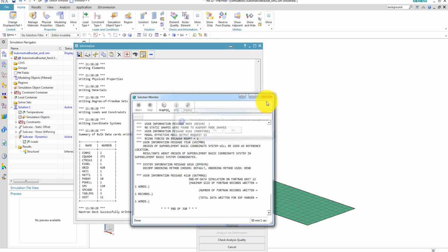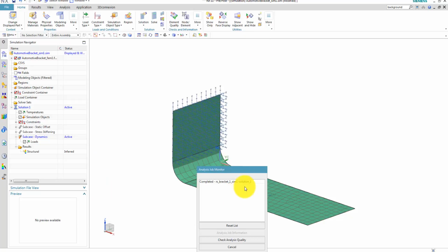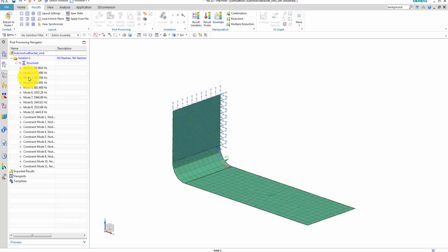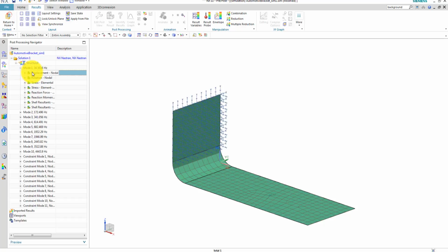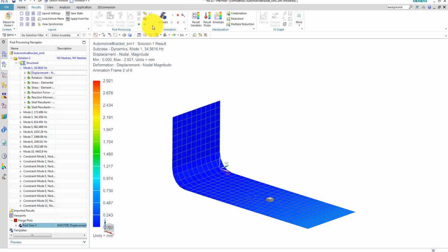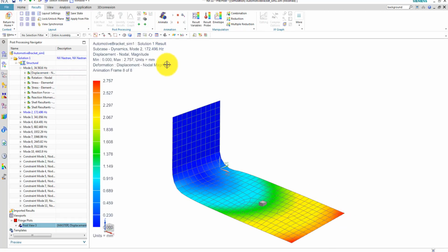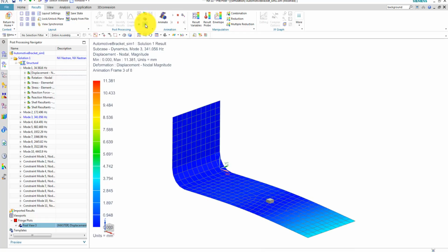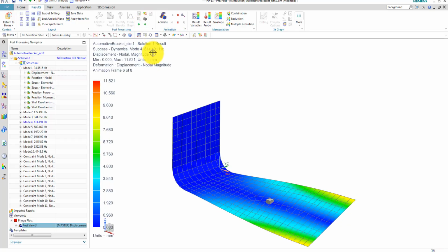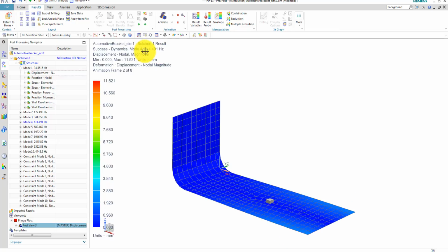There it's finished. And what I've done now is to actually calculate the component modes and the constraint modes that my model gives me. And here you can see the first flexible mode. It has a frequency of 34 hertz. The next one, 172. And the third one, 341. And then it's a big step up to 640, which is the fourth mode.